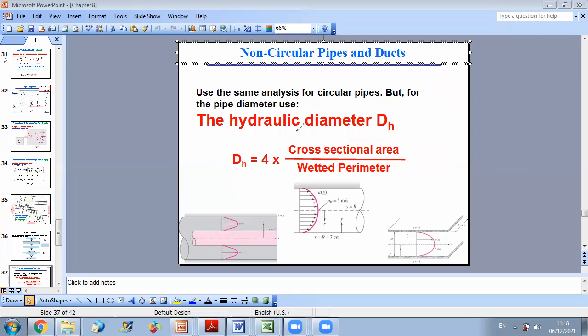Not only is it restricted to circular sections, but it was shown that it also works well for others. Of course, it will not work in all conditions. In general, we specify in which conditions it will work. So they can tell you that for hydraulic diameters in this range, it will work. If it's not working, we should develop a diagram for each section. That is, we should perform experiments again to be able to draw a new diagram specific to the geometry you have.